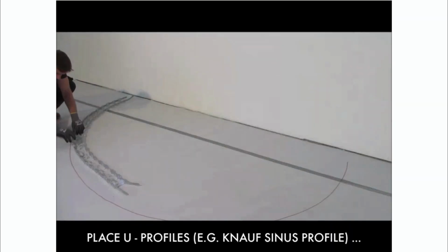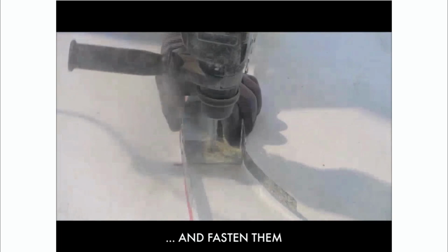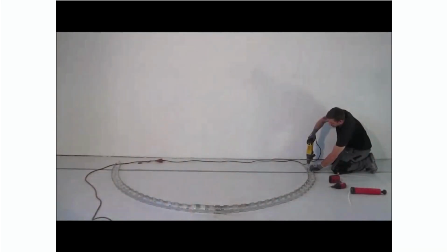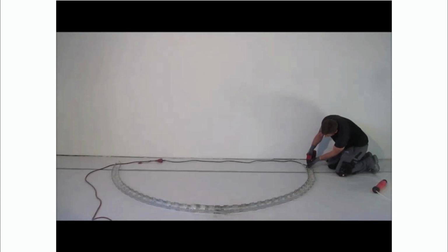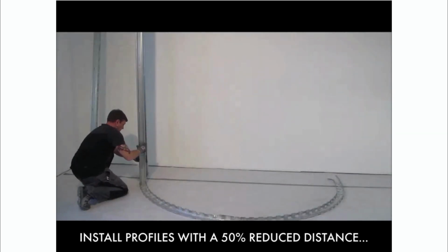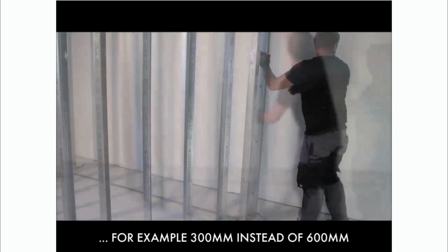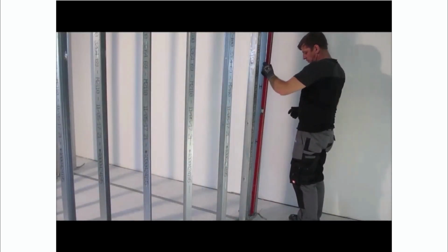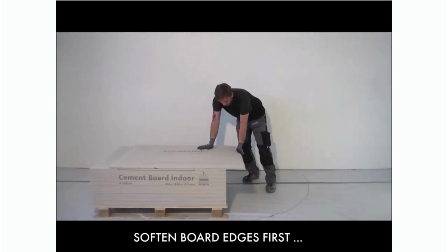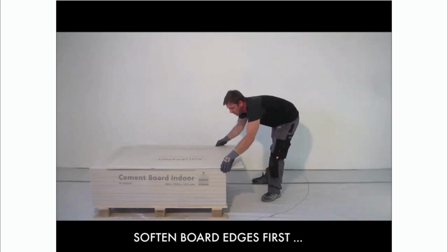Okay, let's understand how it can curve. Using our framing system, at the radius that you require, you place in our flexible track and secure it at both the bottom and the top. Then you put in the vertical elements at a closer interval. Normal drywall requires about 600 mm stud spacing, whereas for curvature, depending on the radius, you may require a closer interval.